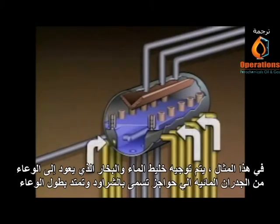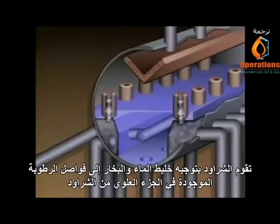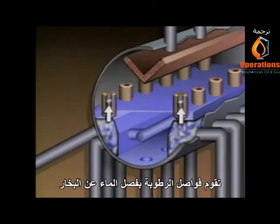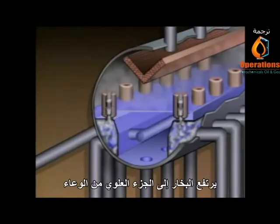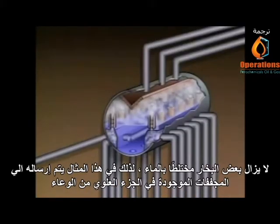In this example, the mixture of water and steam that returns to the drum from the water walls is directed against baffles called drum shrouds that run the length of the drum. The shrouds direct the mixture of water and steam into moisture separators, which are located at the top of the shrouds. The moisture separators separate the water from the steam. The water falls into the lower part of the drum, where it mixes with the feed water. The steam rises into the upper part of the drum. The steam could still have some water mixed in with it. So in this example, it is sent through dryers, which are located in the top of the drum.